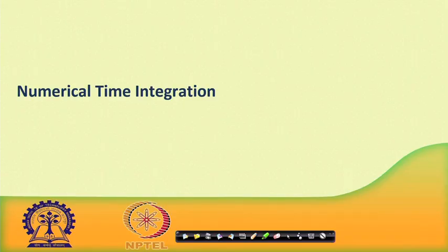Whenever we try to solve a problem, even in industry, people first try to simplify the problem into a smaller problem and try to solve it analytically using techniques like modal analysis, the convolution integral, and harmonic loading with the magnification factor, so as to get an overall idea about the physics of the problem. Once the physics of the problem is understood, then usually people do a large scale analysis. Since we ended the last talk with the example of an aircraft, suppose we are trying to analyze the vibration of a whole aircraft.